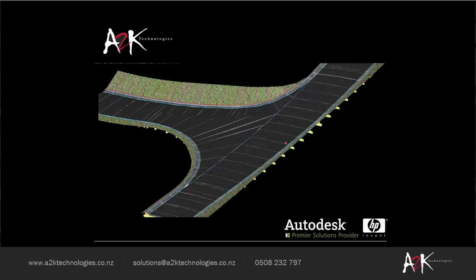The road that I'm going to be joining into, I have manipulated it, played with it, so that the crossfalls are going all over the place. You'll see that from the contours in a moment. So it's not a nice smooth road. It's what you might get if you were taking a real survey on a real road. So we want to get a nice smooth join between the two with our modelling.